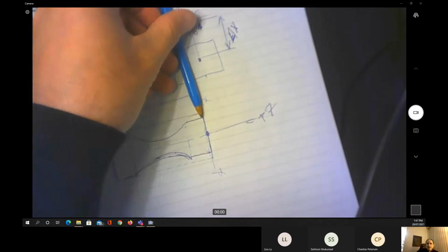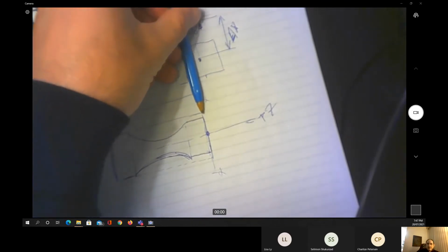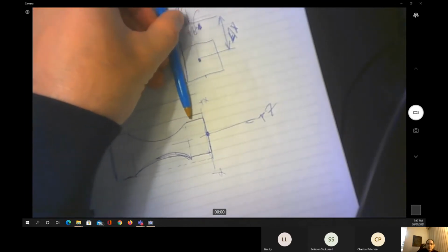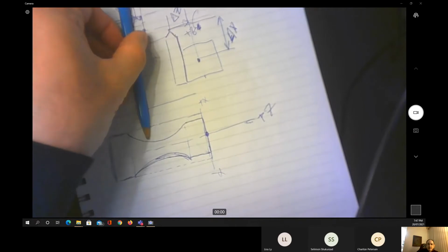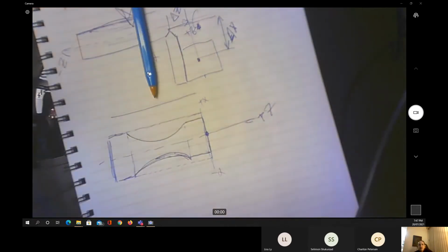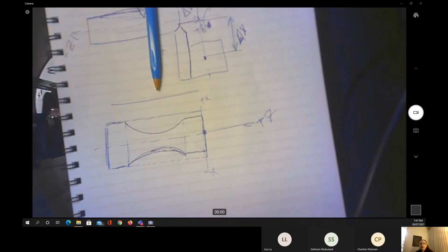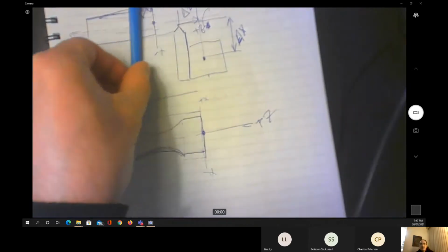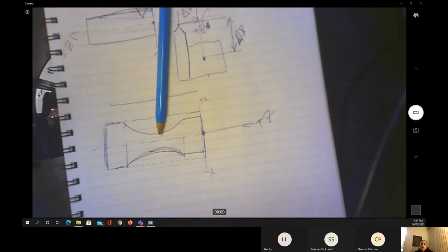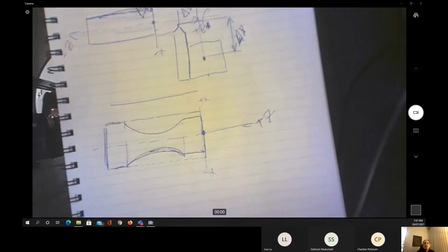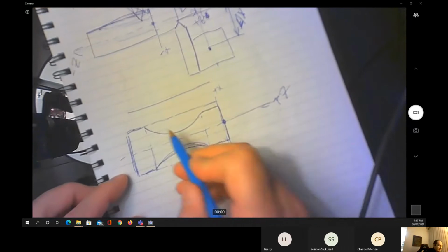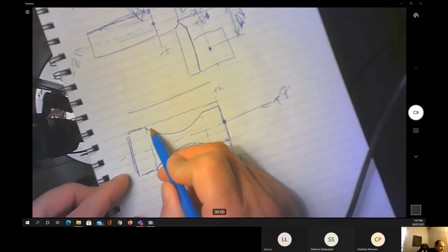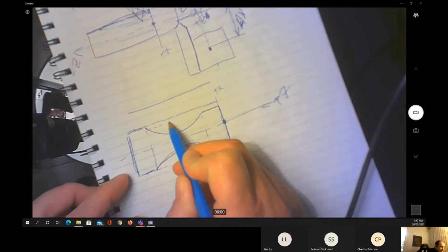Again, I told you that we cannot set the cutting tool to that depth and start to move it in this way in the case of the turning, because we try to minimize the contact between the tip of the cutting tool and the work part. So we always try to do that by steps. So my first cut is going to be as following. I'm going to remove one layer.